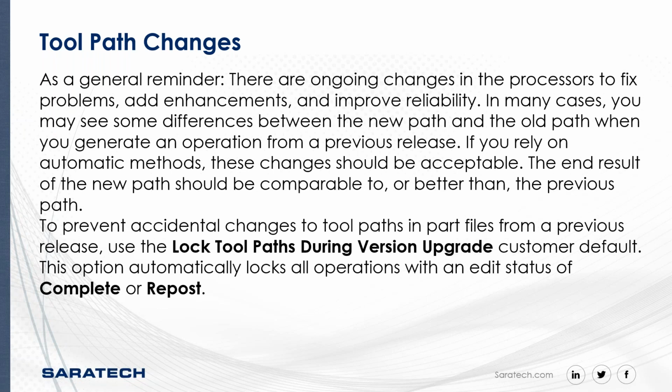This is a general reminder, anytime there is a revision, your tool paths can change. We recommend you check them, and they're hopefully better than they were before, but you always want to check if you've got several programs that you've been running forever and you don't want them to change. You may want to lock the tool paths during version upgrade. It's a checkbox inside the customer defaults.